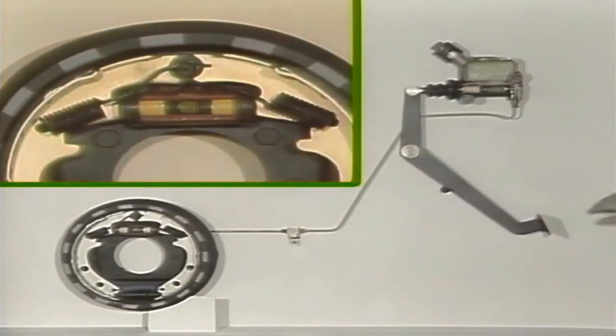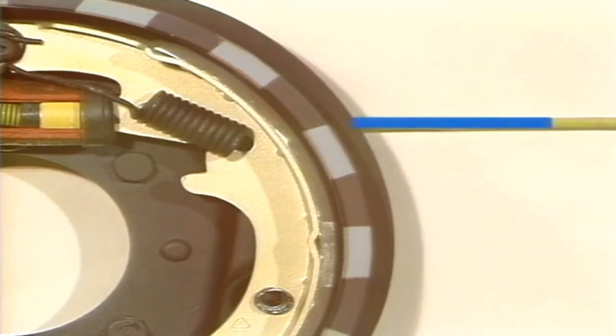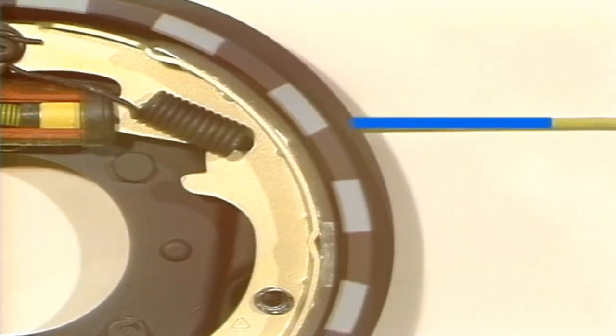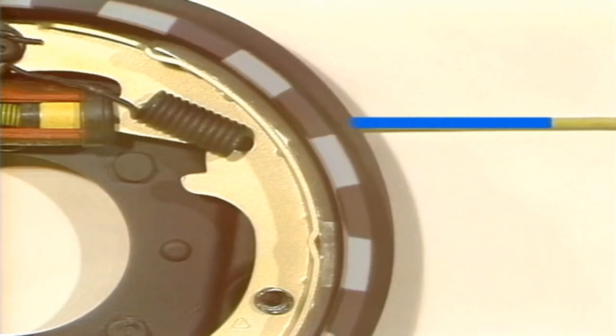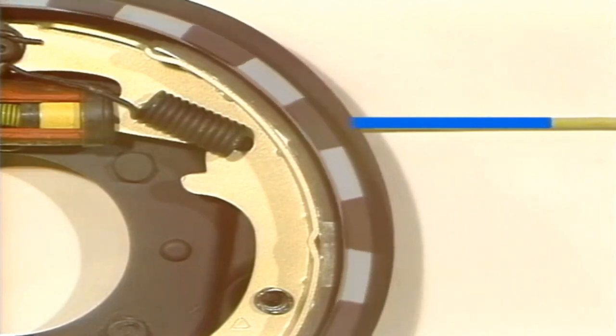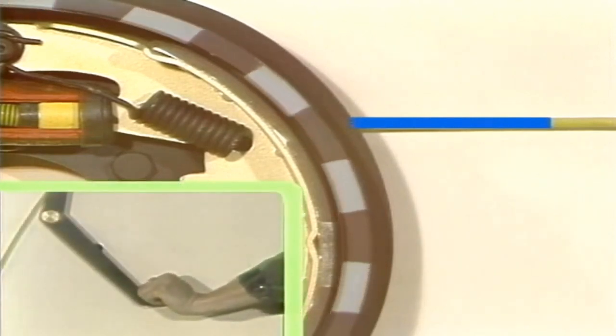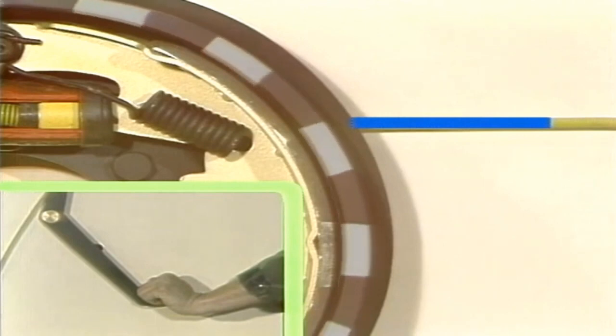Now, let's say some air is trapped in the brake line, near a wheel cylinder like this. Air is compressible, and that can cause problems. Let's again push down on the brake pedal until the brake linings make first contact with the brake drum. So far so good. But now let's push down harder. Here's where the problem shows up.